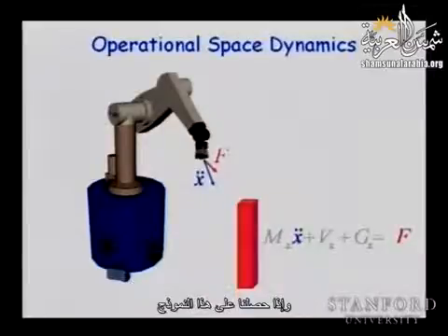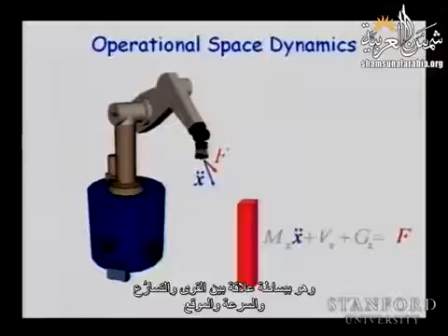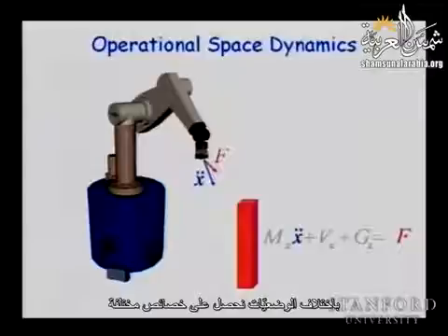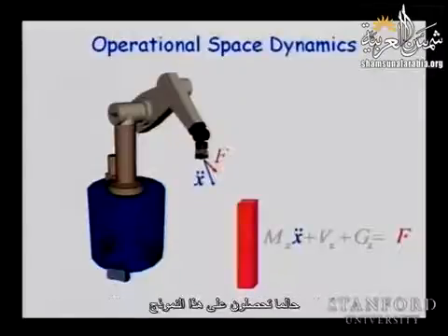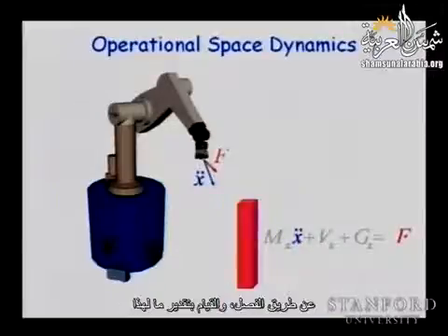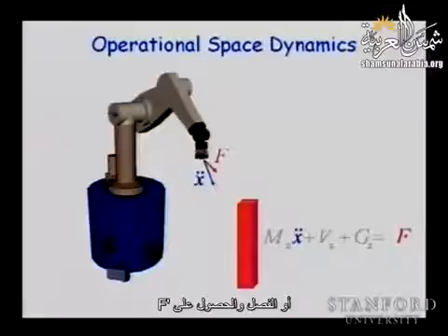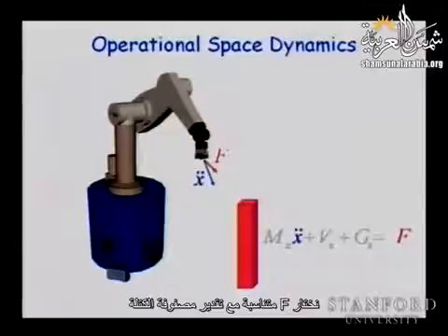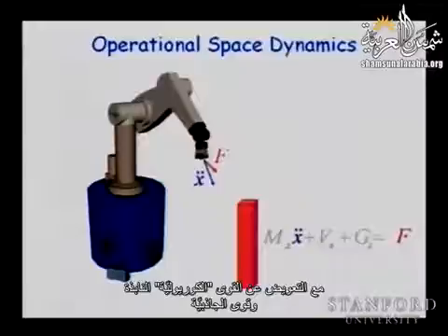And if we obtain this model, which is simply a relationship between forces and acceleration, velocities and positions, at a different configuration you have different properties. Once you have this model, you can do the same thing we did with controlling the robot in joint space, by decoupling, making an estimate of this, decoupling, and making an F star or F prime. Now we select an F that is proportional to the estimate of the mass matrix, with compensations of centrifugal, Coriolis, and gravity forces.